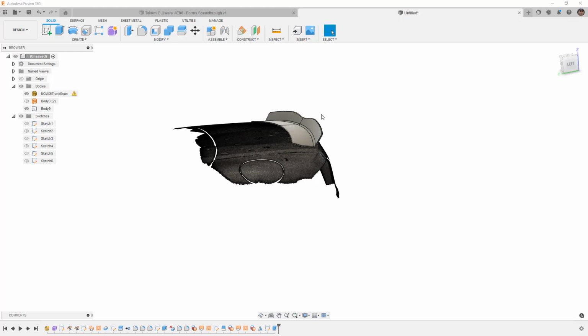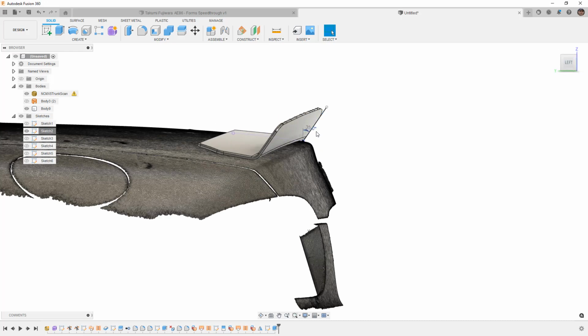Anytime you're making a design like this, it's not going to be something that is parametrically controlled and easy to update. So spending a bunch of time dimensioning everything and trying to build it so that you can just tweak some values is probably not going to be realistic. We could go back to the sketch where we had 35 degrees and likely change that and adjust this. If I show this sketch and I show the dimensions, there is a slim possibility that I could modify this to say 30 degrees and have it all update. Chances are slim once we start tweaking things so that we have surface blends. You can see here it ends up failing.